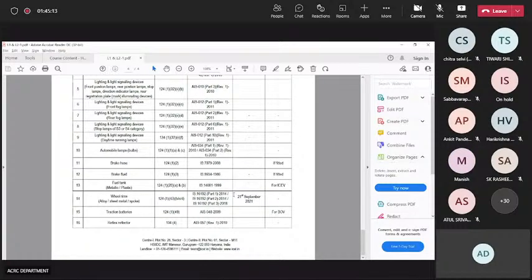So basically, that is the general idea of how many components are critical and have to be certified for any vehicle you are going to manufacture or sell in the market. Once this part level certification is done, or you are using an already certified part, let's say you have a wheel rim which is already certified by some other supplier, you will ask them for the wheel rim with the certificate so that you don't have to do the certification again. You use the same wheel rim with that particular certificate, with that particular load condition matching your vehicle application, and you go ahead with that one certificate. You don't have to pay again.